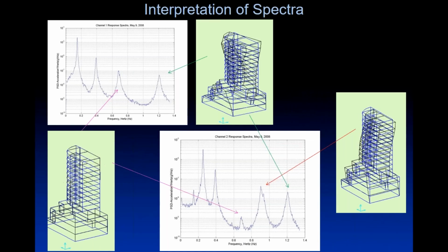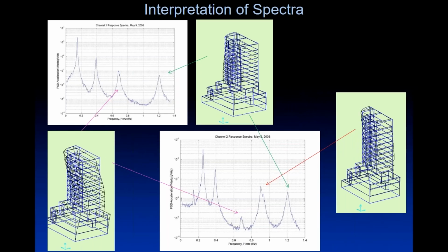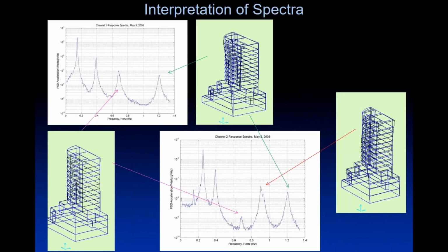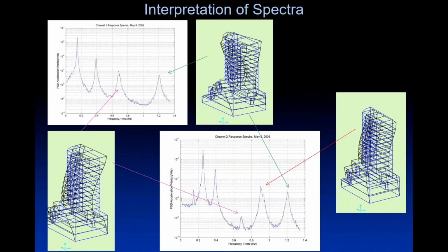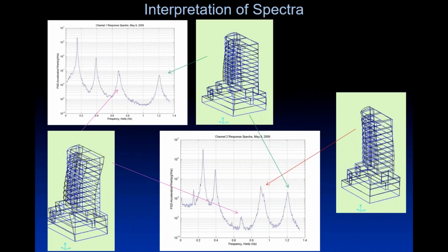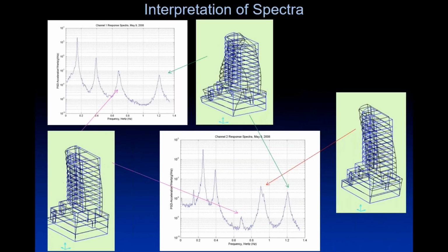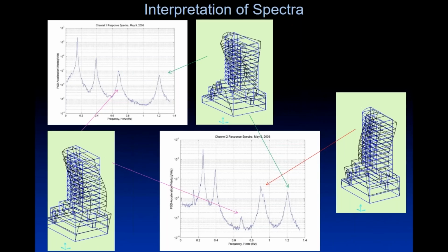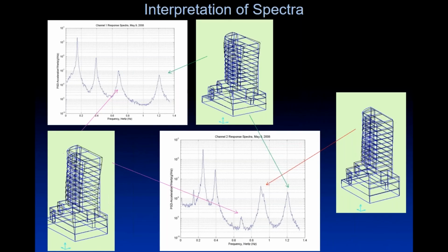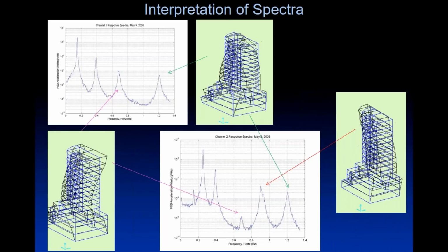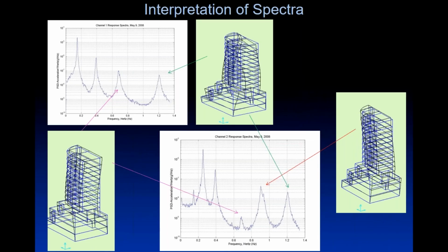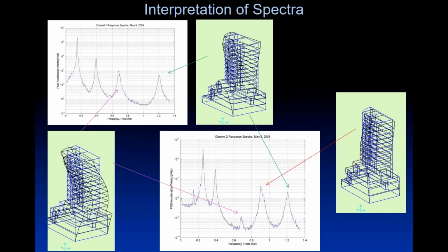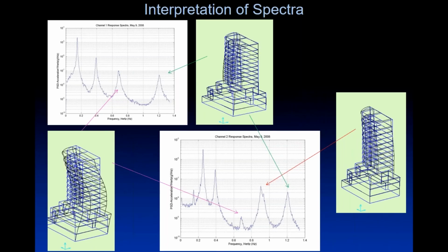If we've got this middle one, torsion, then we're monitoring in both of those orthogonal directions. We are getting 0.4 hertz. So we can see that. Let me draw your attention, though, to the bottom left of this diagram where the building is swaying in the east-west direction. Let's just look at what's going on near the foundations here. And I'm going to move up in frequency and see more complex modes of vibration, and this is what we get. Okay? Looking at that bottom left side, we've got more motion at the foundation level of the structure.